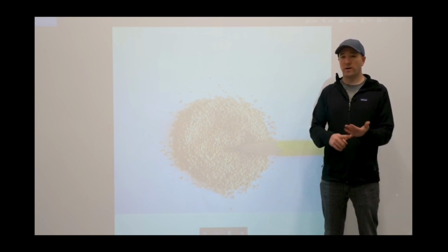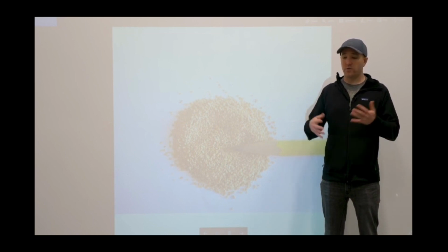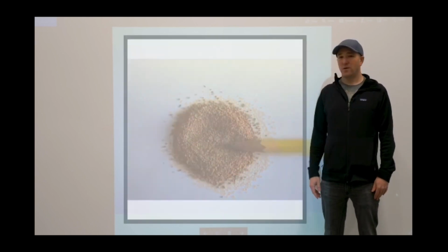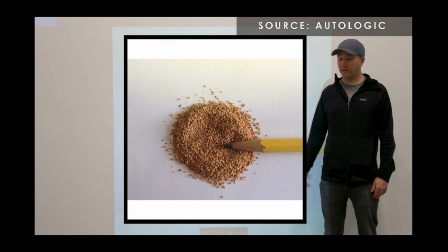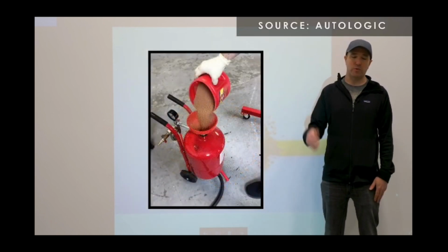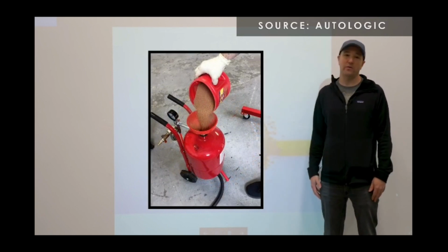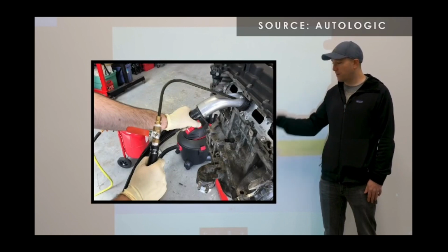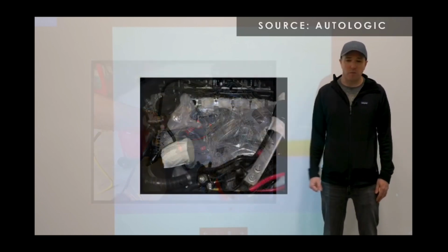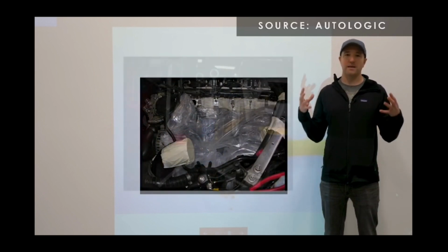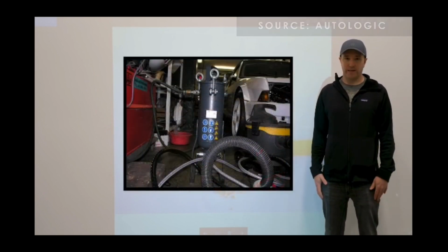Now, if you don't want to run a catch can, a good one, and you don't want to deal with trying to figure out a better oil to run, then you're left with this walnut shell blasting media, because this is what you're going to be shooting into those intake valves, into that intake manifold through the ports of your engine to clean out the valves every 30 to 60,000 miles to keep it running optimal. You can do the chemical way, you can do the Brillo pad, you can use the drill way, but this is one of the best ways to get the valve train clean again.